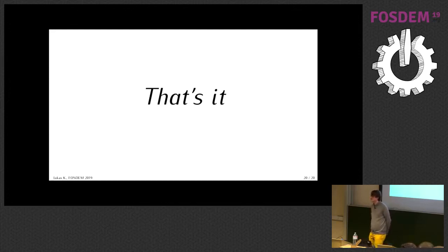Are you having any support for bus routing? So, bus definition and or routing? Okay, so the question was whether there's support for bus definition and bus routing. Bus definitions are supported, so they're actual buses, not just names in the schematic. But bus routing isn't supported, since all of the routing stuff is pretty much just the KiCad router, and the KiCad router doesn't support bus routing yet. But if they happen to add it, I will likely adapt it as well. Just wanted to say that it's probably going to happen during the version 6 development cycle, but I don't want to make any hard promises.